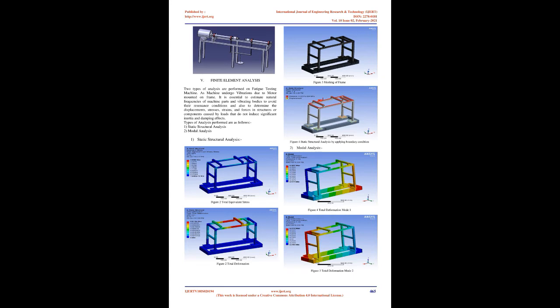Drill chuck. The metal desk on which the system is assembled is made with 3 mm angle iron of mild steel and a plain pan made of mild steel for the top. The length of the desk is 760 mm, and the width and the height are respectively 210 mm and 190 mm. The desk is drilled at each point where parts are to fit with bolt and nut. A rectangular opening is found through which the hanger is passed. This is located at the top of the desk.